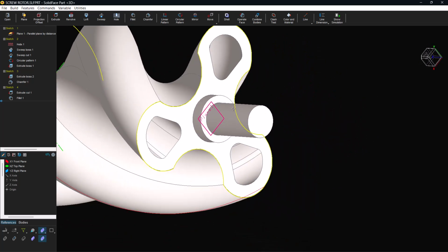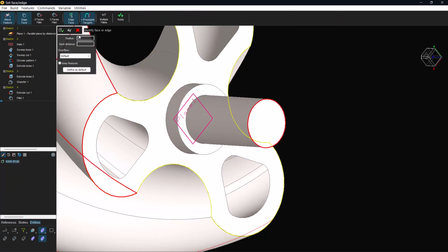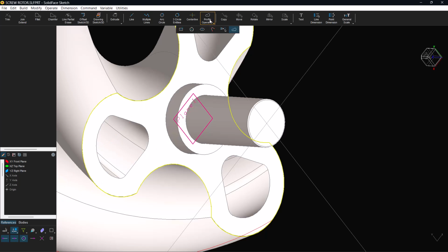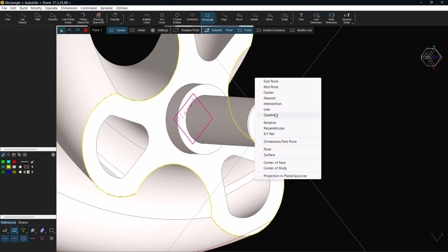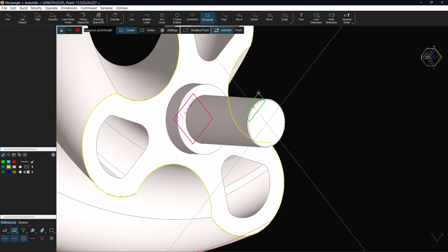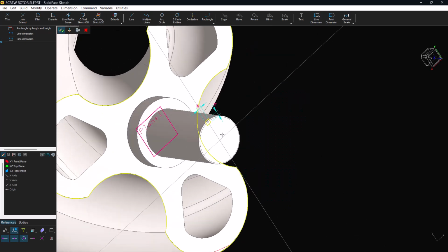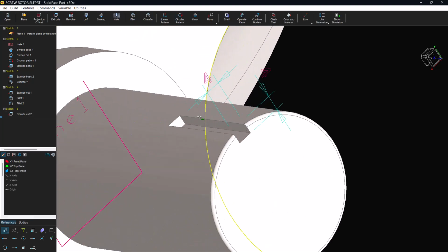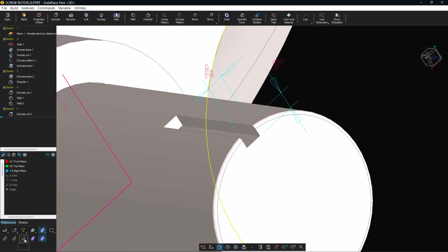Create grooves on the other axis. With fillet of 0.8, create sketch and rectangle with center in the quadrant. Extrusion of 30. And fillet of 2.